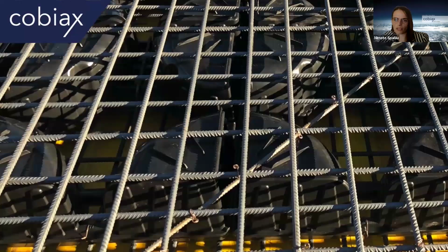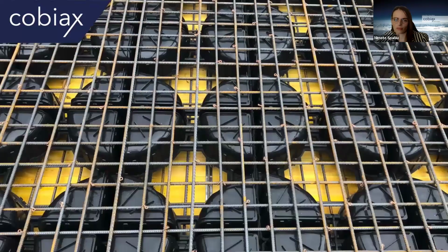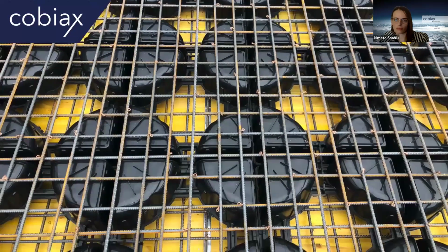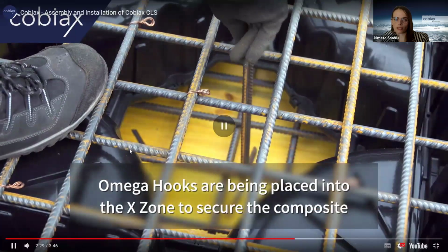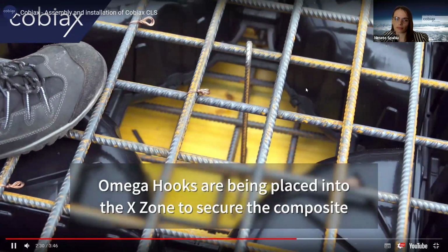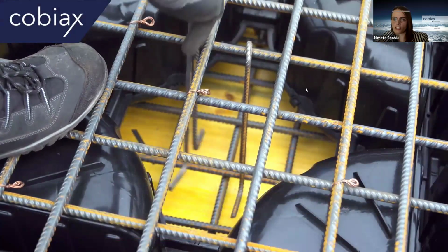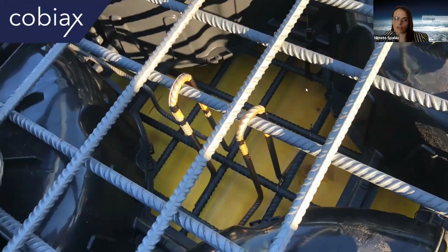This is the top reinforcement layer that is now laid down. Those are the omega hooks or bonding reinforcement that I said we put. We hang them over the top reinforcement, and they serve to link the bottom layer with the top layer of the concrete. Two of them in each X zone. We just have to hang them on the top reinforcement. It's very easy.